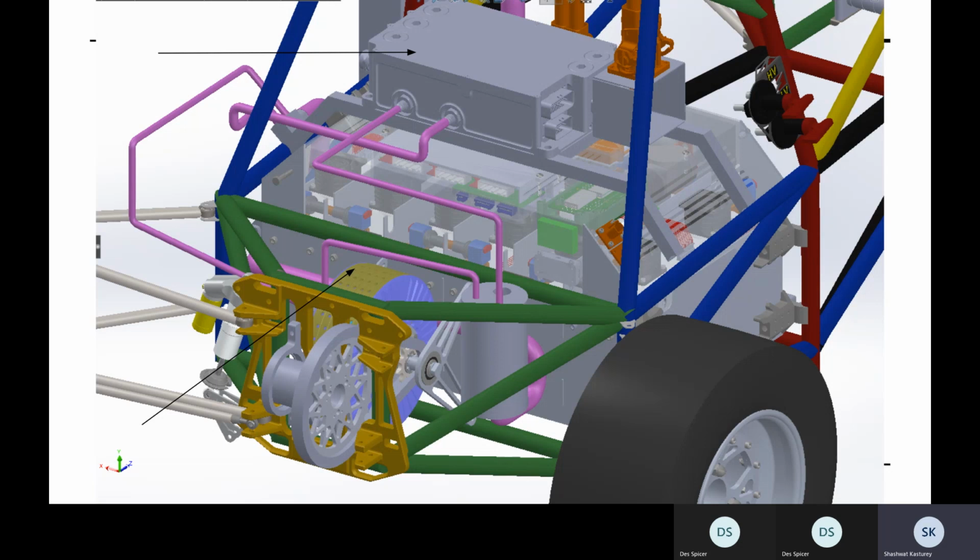Thermal runaway is the word for the state they're in at that point. If you get cooler than 45C, they actually discharge less. So there's a happy amount of heat that the cells want to stay at. We're just aiming between 45 and 60C.